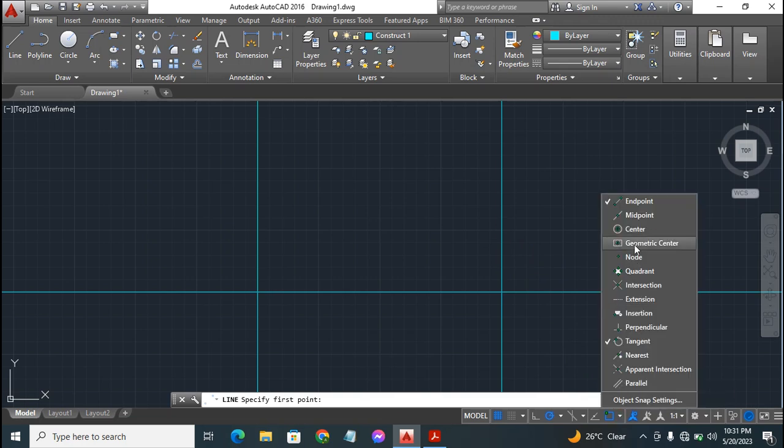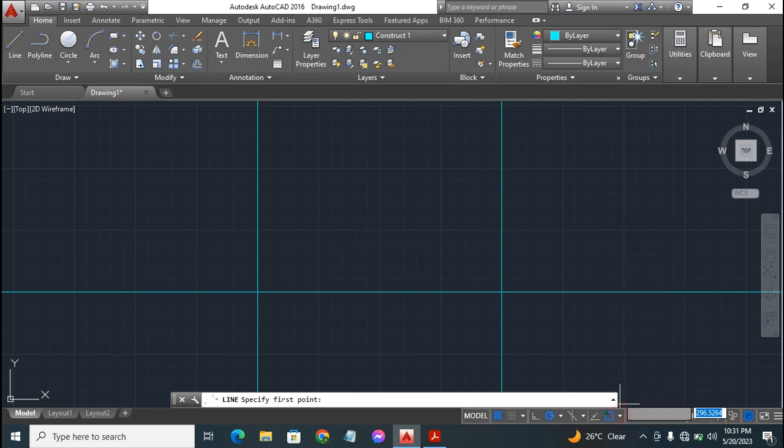Okay, the drop down for just now. I'll select intersection. It's not selected, that's why it's not locking to that point of intersection. So I'll still need midpoint, need center. Alright, so yeah, I guess this will do for now. So we'll leave that. So let's try that again. Now you see, now it locks to that point of intersection. Right, so I'll lock it down there.